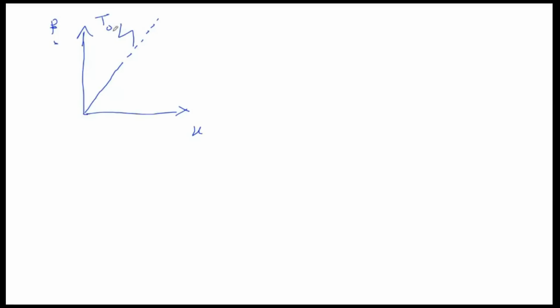So if we use that, this is the elastic behavior. This system will experience a base shear. Let's say that this is V elastic. So this V elastic will be equal to the Fs for that T naught. But in reality, the structure always has a force deformation behavior which can be idealized, in most cases, as elastoplastic. So this is the elastoplastic behavior.